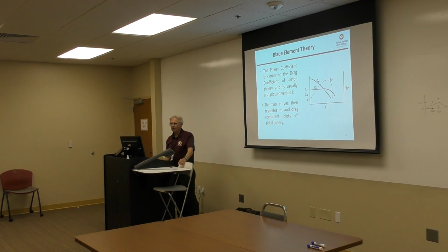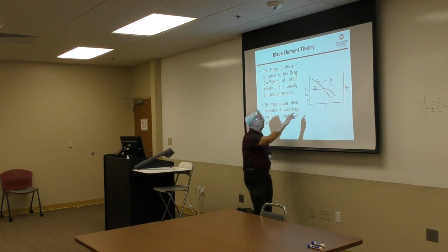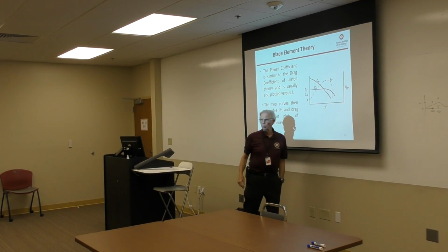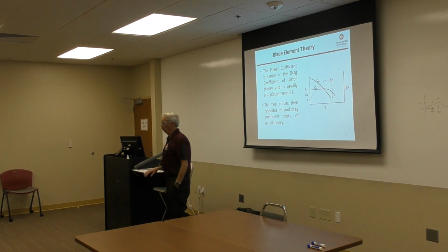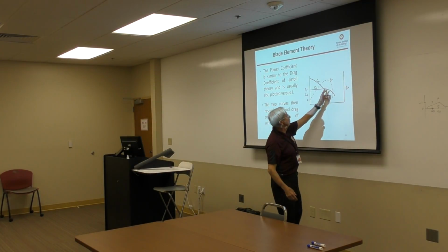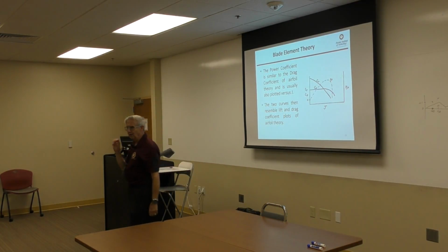Now, that's just for a single propeller element. And from that, what we see is this single, fixed pitch propeller has one place where it is the most efficient. I say one place, one advance ratio, and remember J equals V, velocity, over ND.